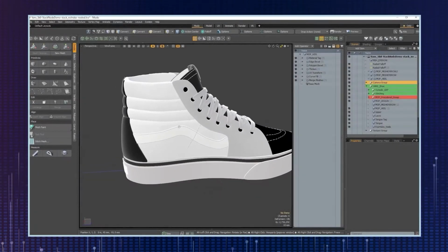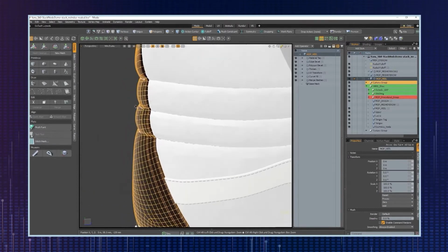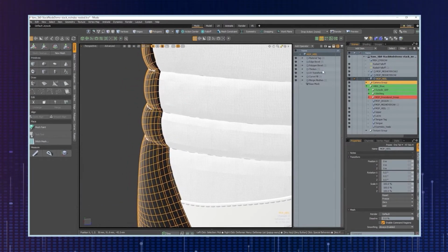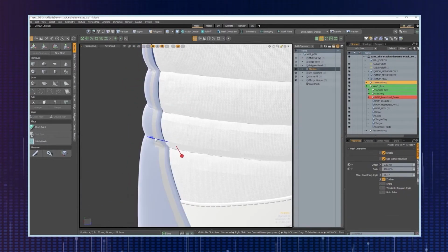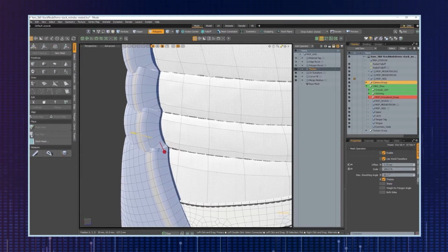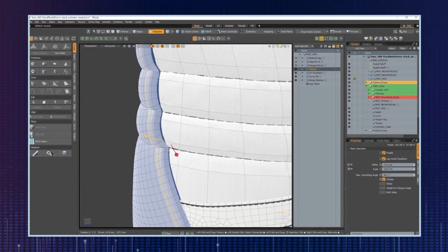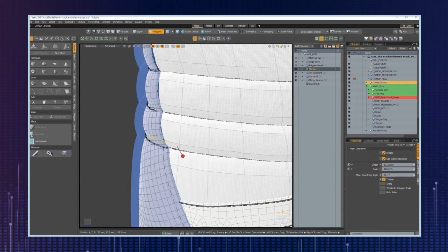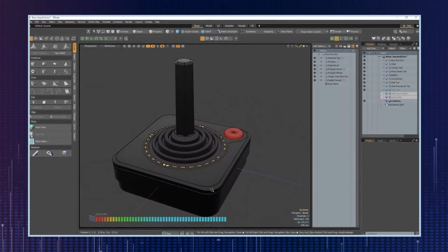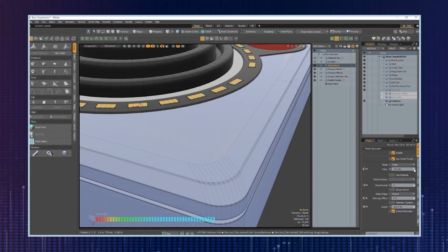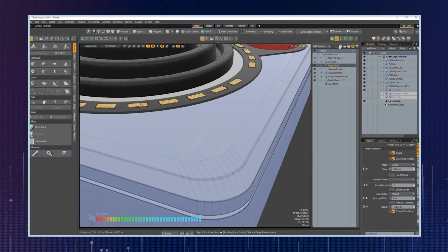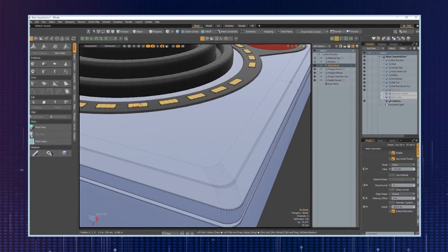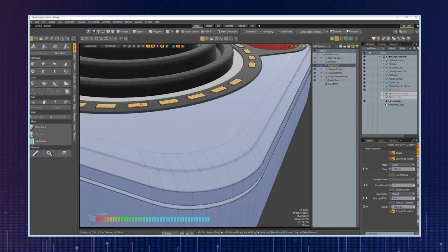Mesh ops allow for modeling operations and deformations to be performed in a sequence, and each operation can be modified at any time in the creation process. While this workflow empowers you with a non-destructive approach to modeling, it also means that when a change occurs, every operation in the stack is re-evaluated. This creates performance challenges when a stack becomes large or contains many operations. Deferred evaluation makes modifying channels anywhere in the stack more interactive by deferring the update through the stack until the user releases the mouse, producing a more comfortable experience interacting with complex mesh op stacks.